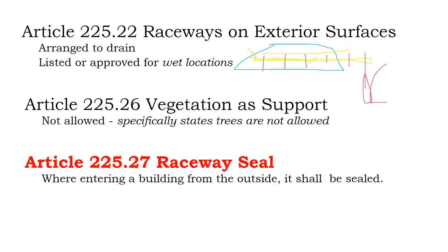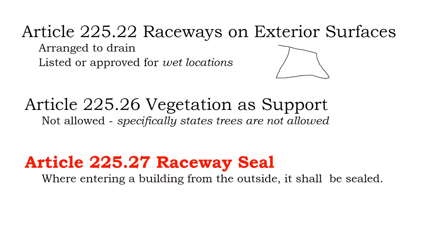I prefer the trough method of solar because it provides good physical protection against debris and against rodents, which is a different kind of hazard. But even so, you need to arrange the cables to drain. If you have a module level box up on the rooftop, you can't go into the top of the box where water could get into the box.